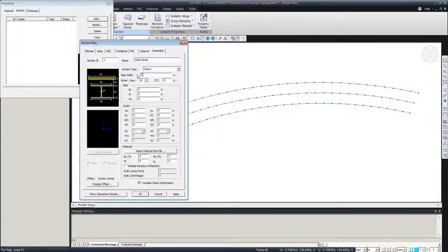All right, so let me enter those. And if you don't want to consider the lateral stiffness of the bridge, you can enter them as the same as the slab width and so on. So this is what I'm doing. I'm entering 120 and I enter 1 girder and I keep this center to center as 0, so I'm not seeing that effect in my analysis. So I'm just defining this. The effective width is going to be 120 inches and the thickness is going to be 8 inches. If I have any haunch, I can enter it, but I don't have any in this project.